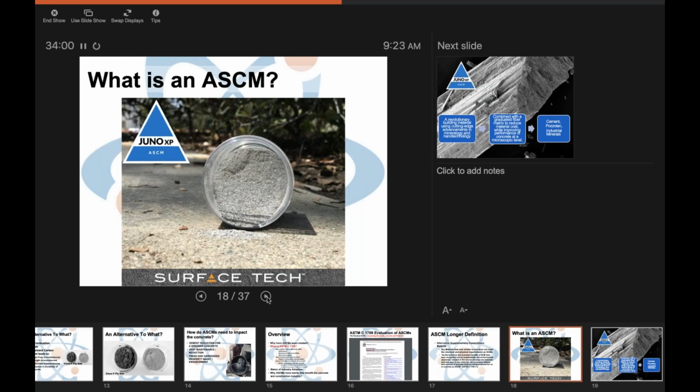Now, if you notice it on your screen, it's somewhere between the fineness of cement and the coarseness of a masonry sand, an ASTM C1044 sand. And we've done that on purpose. There's two very specific technologies, and I want to talk about it in a mechanical and chemical way. And what I mean by that is, when I first came into the industry, we started using multiple coarse and fine aggregates in our self-consolidating concrete to make the concrete robust.